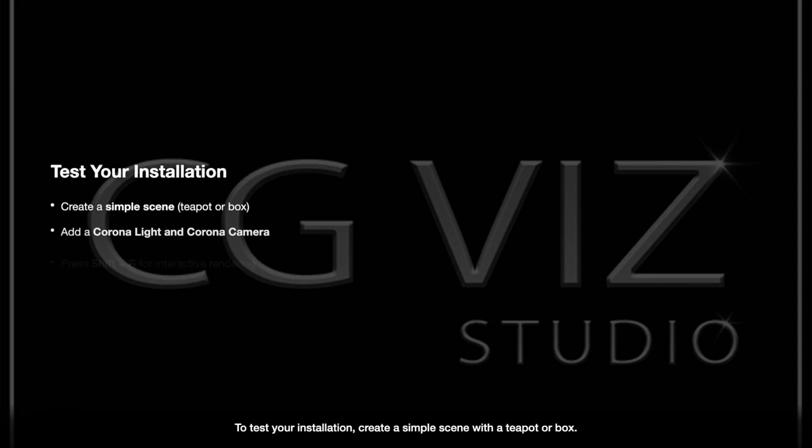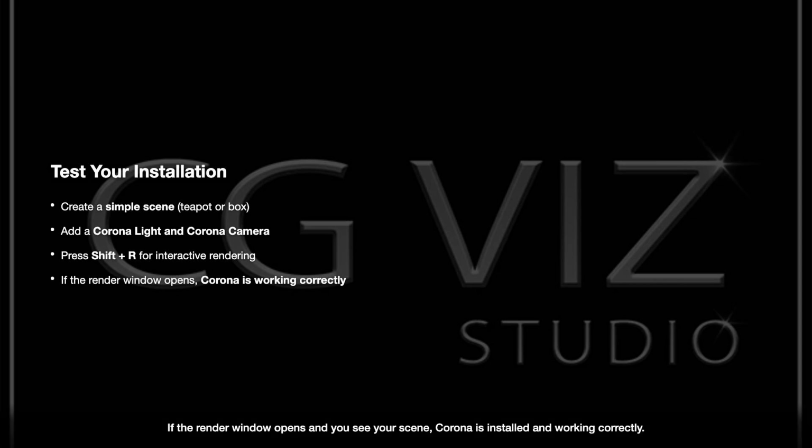To test your installation, create a simple scene with a teapot or box. Add a Corona light and a Corona camera to your scene. Press Shift+R to start interactive rendering. If the render window opens and you see your scene, Corona is installed and working correctly.